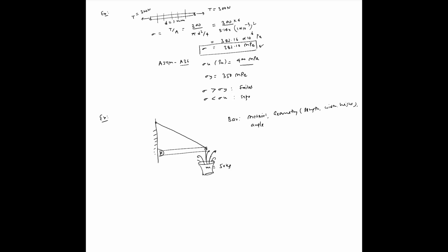In this case, it's shown to be completely horizontal, but it didn't have to be that way. Same kinds of questions exist for the wire also. What kind of material should the wire be made of? What should be its diameter? Because the larger the diameter, we know the normal stress would be less. What angle should it be making from horizontal?